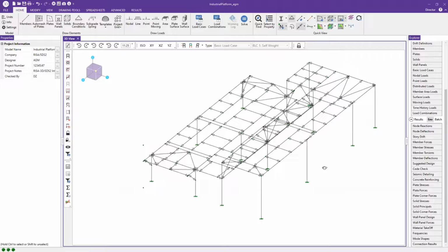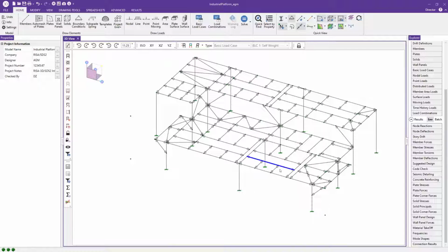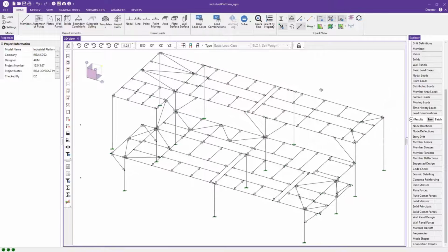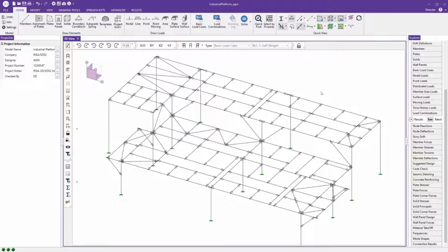All right, so one last thing that I want to point out, something that was pointed out to me in a webinar about delegated connection design a million years ago, and now I'll pass it on to you folks. David's going to be talking a lot about how much of the value this adds to your project is that very often we're designing connections for just the ultimate distributed load that a member can handle, or some other factor that's going to give you a very, very conservative and very heavy connection that's going to just cost a lot more money.